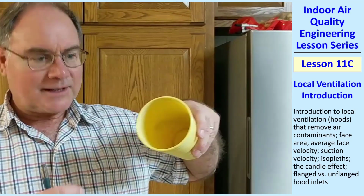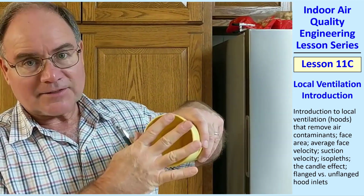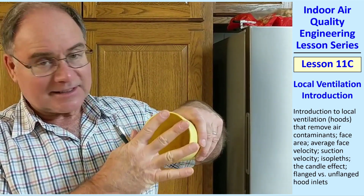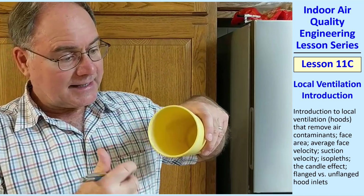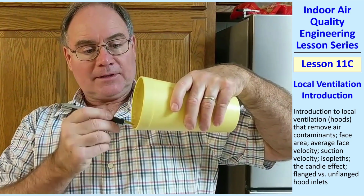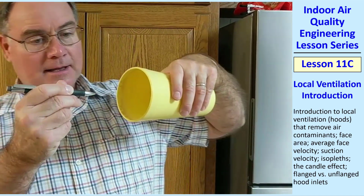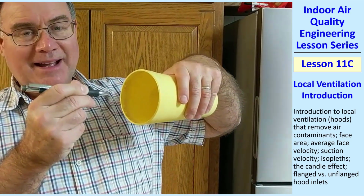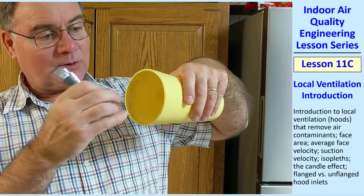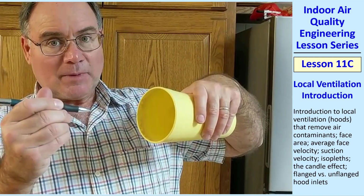If I take a round inlet, let's suppose this is a suction device, and this is the face. The face velocity is the average speed through that inlet. And if I put a probe about 1 diameter away, right at the center line, the speed there is about 7% of what it is at the face. And it decays very rapidly as you go back.